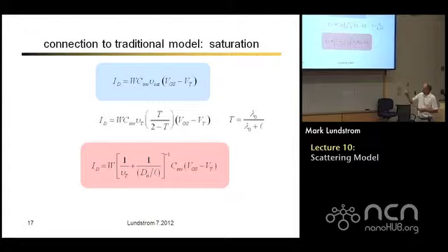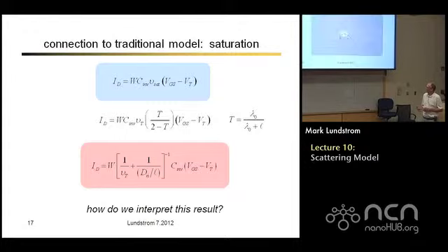W, you see the W there, the C there, the Vg minus Vt. Instead of Vsat, we have 1 over the thermal velocity plus 1 over the diffusion coefficient divided by the length of that mean free path. Now, the length of that bottleneck region. All right, so that actually makes a lot of sense. So let's take a look at that.